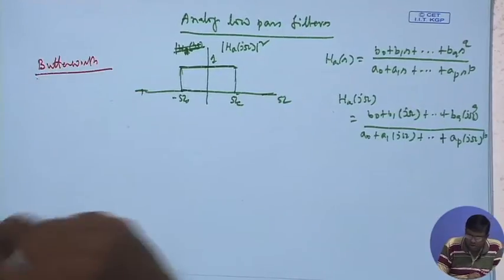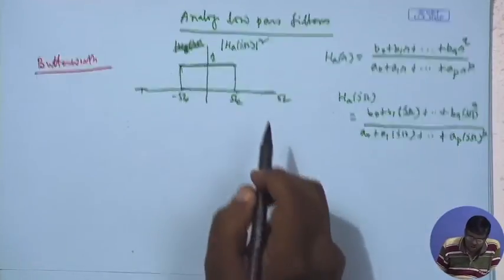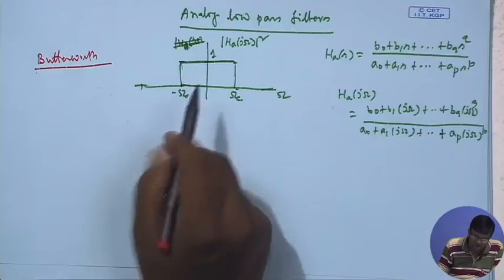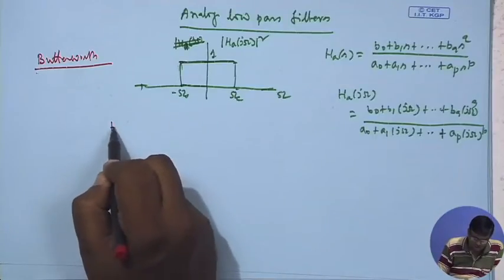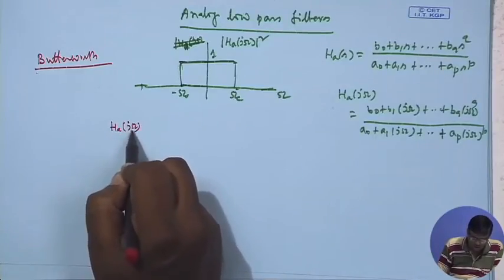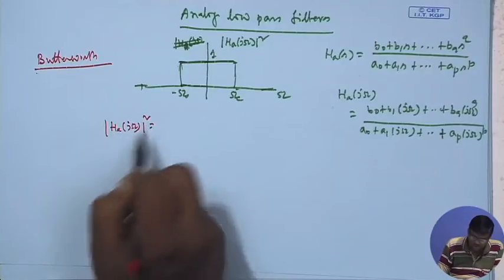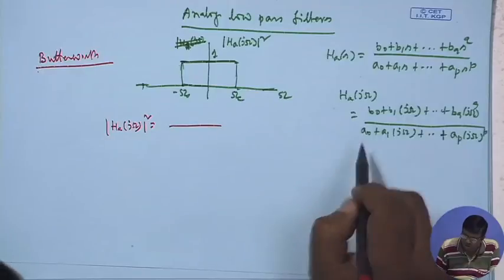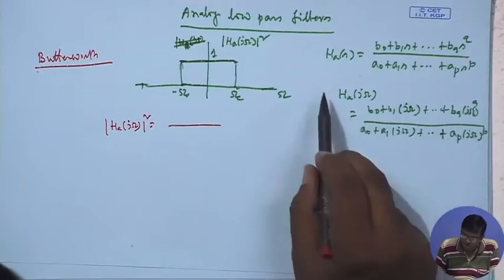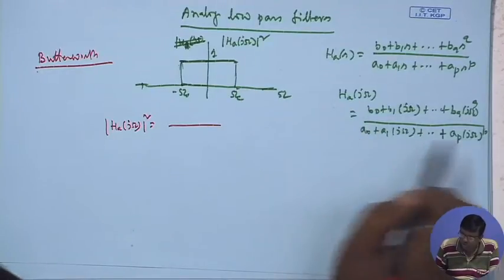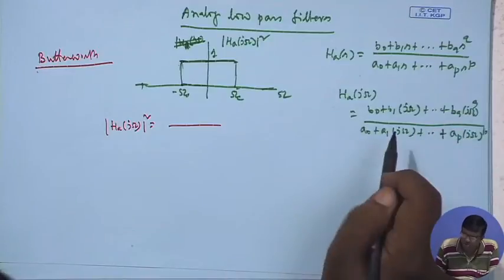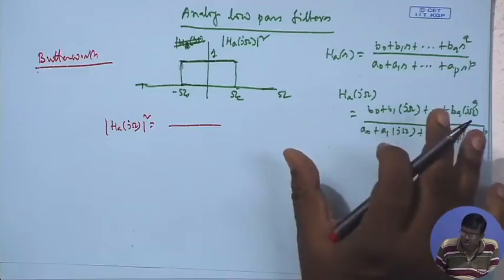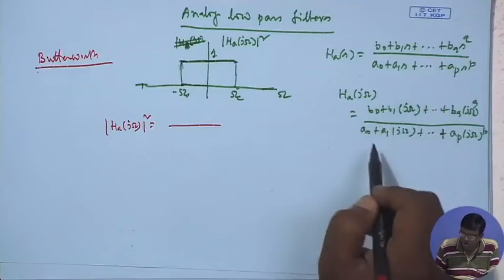Okay. Here, you try to approximate this desired function by this. This should be rational, because H A(j omega) is rational. So, if you take the mod of H(j omega), there is the mod of the numerator by the mod of the denominator, and if you square up, it will still be rational, with powers of omega in the numerator and the denominator also.